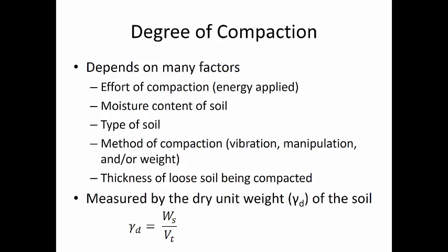Okay, so now that we understand the benefit, let's talk about how we determine that. Well, the degree of compaction really depends on lots of different things. To reduce the void ratio in soils, you really need to make sure that you understand the mechanism that goes into densification of soil. First, the amount of energy being applied becomes very important. That's obvious. The more load and effort and energy being applied to the soil, the better compaction will be achieved.